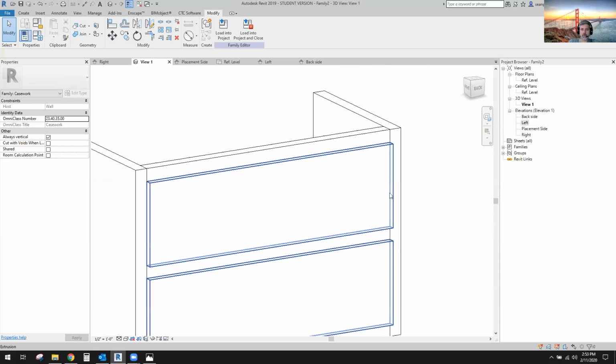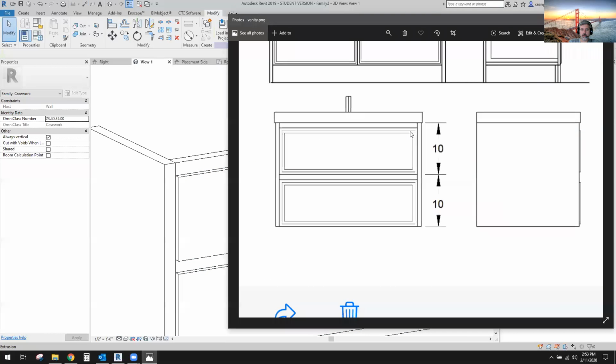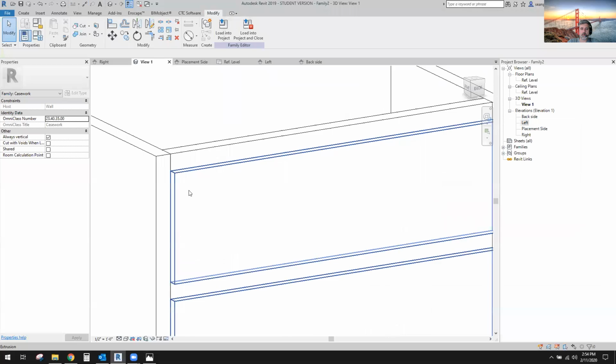Now we need to put in that design that wraps that edge. If you look, there's this bevel right here. So it's flat on this side, but it's curved on this side. So I think a sweep is going to be the best way to handle that particular situation. Let me check the video I got earlier and make sure that I'm curving this in the proper direction. Okay, so it's not a very high profile.